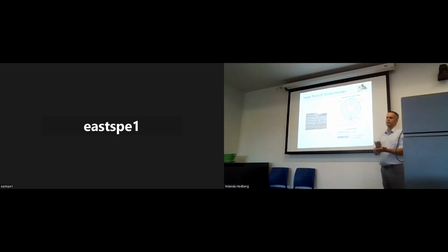the civil engineer is stuck in their ways, they designed it, like, hey, this is what we're doing. And then, oh yeah, we've got to put cathodic protection on that. So, hey, cathodic protection engineer, get over here. In some cases they'll have a dielectric liner that's like a foot, 30 centimeters, away from the tank wall. And you're like, we can't put anodes into a foot.